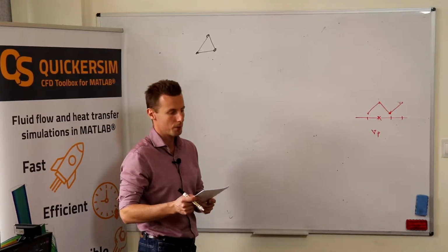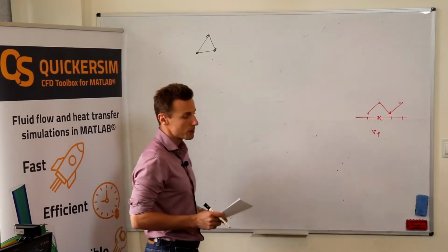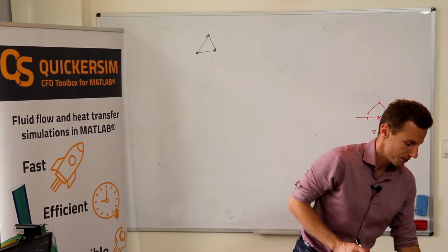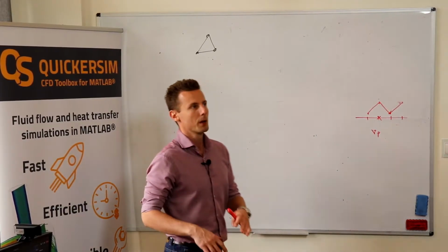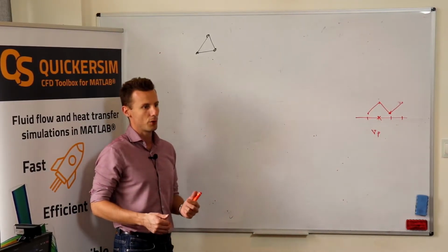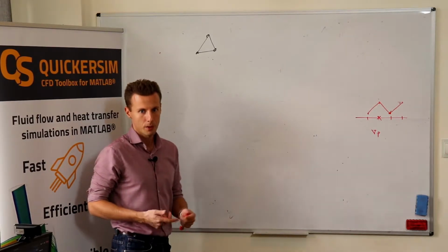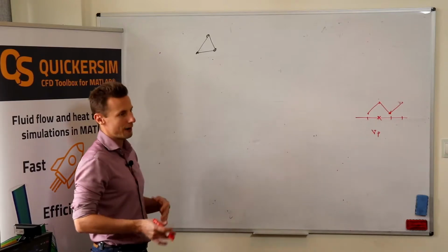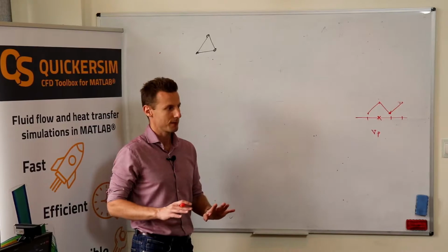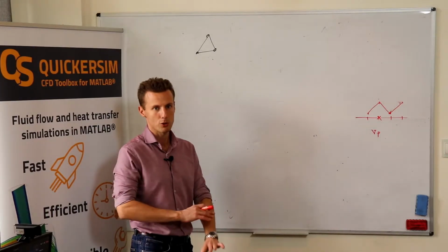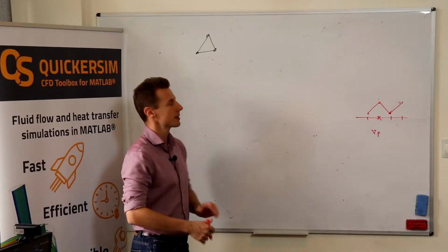What's the most common solution to this problem? The most common solution is that in finite elements we introduce two different function spaces for representation of velocity and pressure. And people have investigated different pairs of these function spaces which make sense and which generate stable pairs.